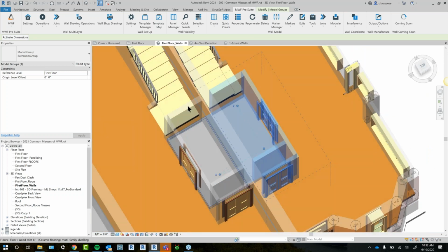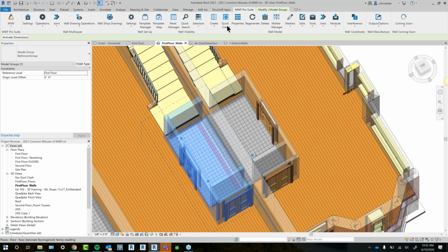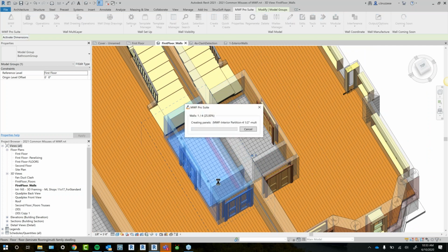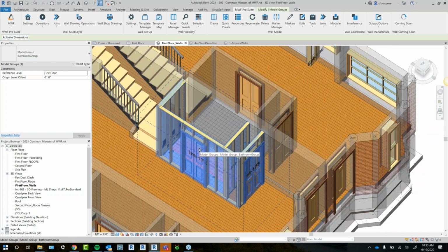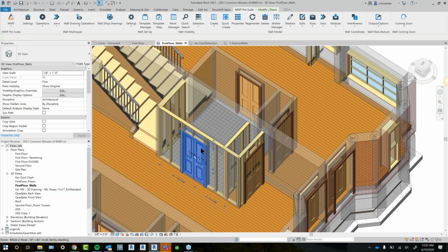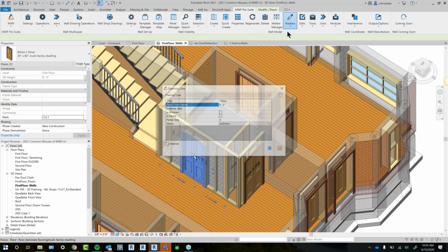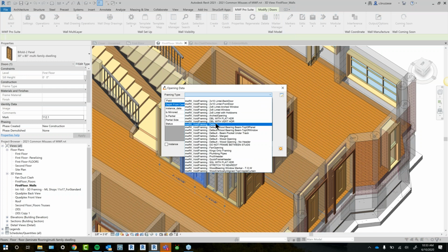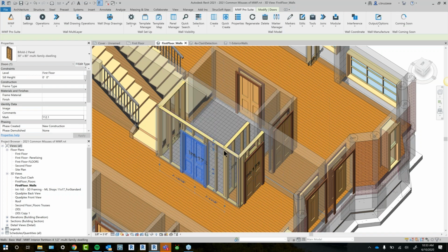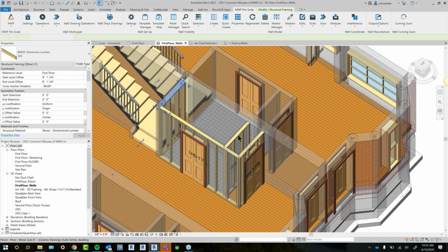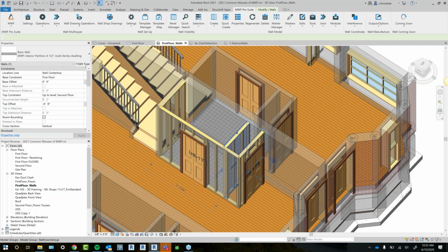If I were to go ahead and let's frame out a group over here. If I were to go ahead and frame this group and manually apply markers, because I'm actually grabbing a family and applying a parameter to it, if I go ahead and apply a marker, and let's enable that, you can see here now that as I click around, it actually broke my group.